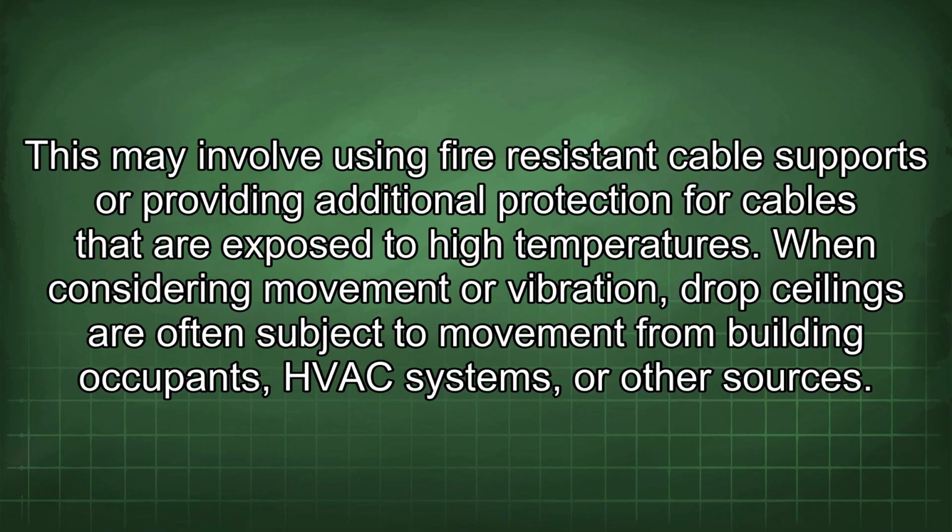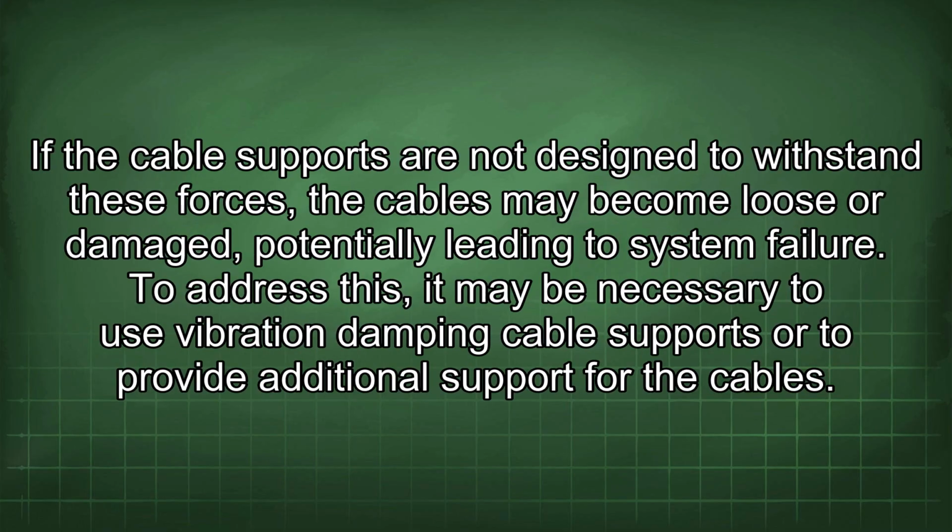When considering movement or vibration, drop ceilings are often subject to movement from building occupants, HVAC systems, or other sources. If the cable supports are not designed to withstand these forces, the cables may become loose or damaged, potentially leading to system failure. To address this, it may be necessary to use vibration damping cable supports or to provide additional support for the cables.